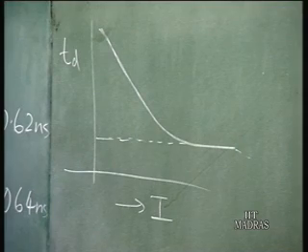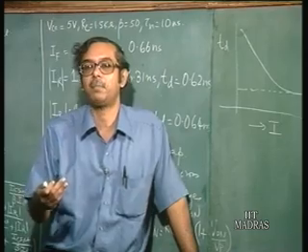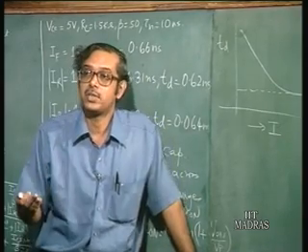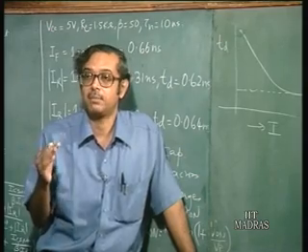So, if you want to increase the maximum speed at which a circuit can be operated, you have to reduce the storage delay time. That is very important.